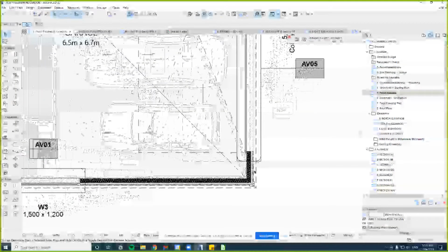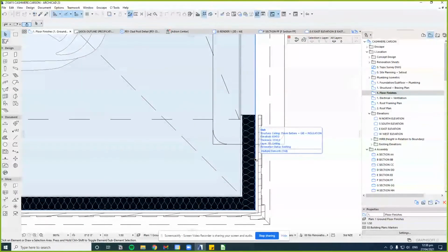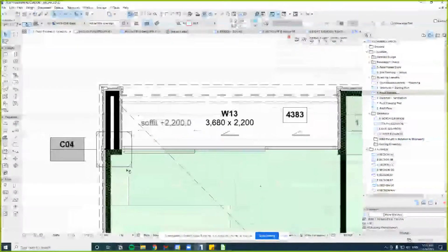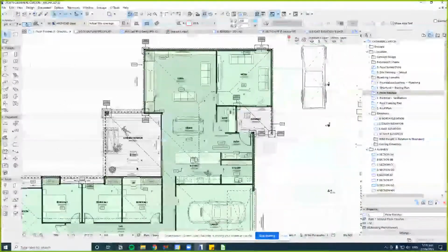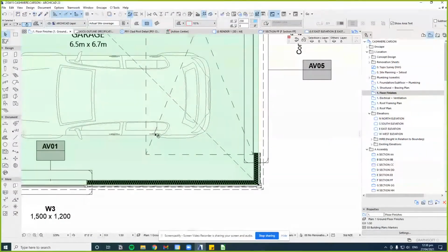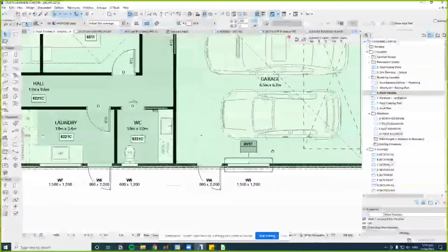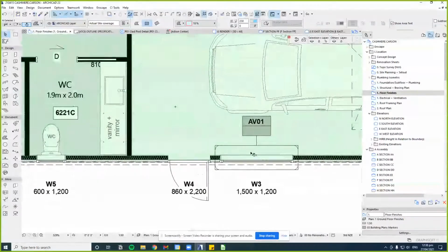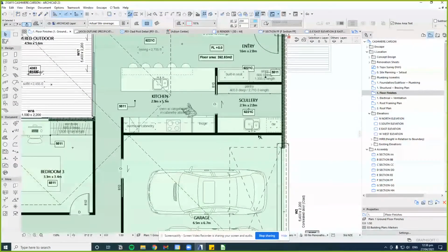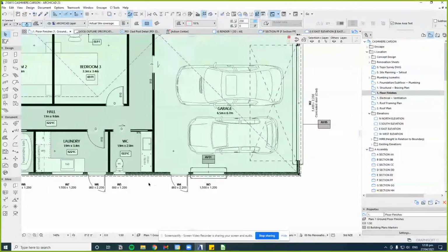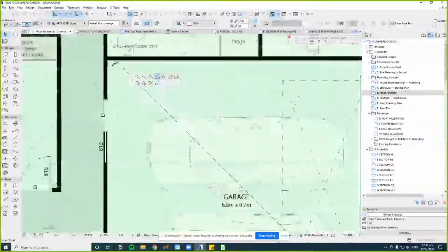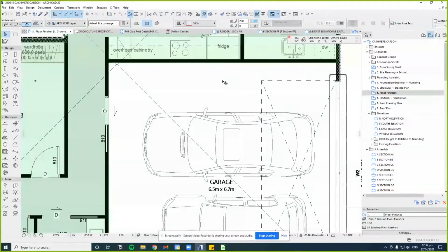Sweet, so I have gone around and I've put this fill in. It is only around the insulated walls. In some cases, a garage will be insulated, and in other cases, it will not be. In our case, on this job, the garage is to be insulated with an insulated garage door, so I've gone around that. If your garage isn't going to be insulated, these internal walls here would be, and I would just have my fill run around the garage like so.